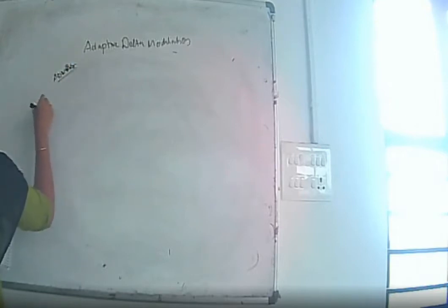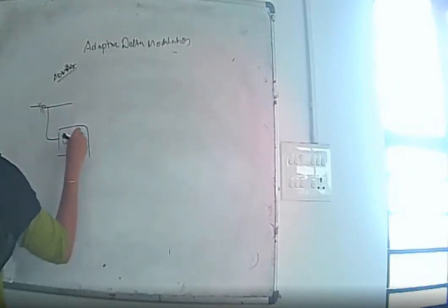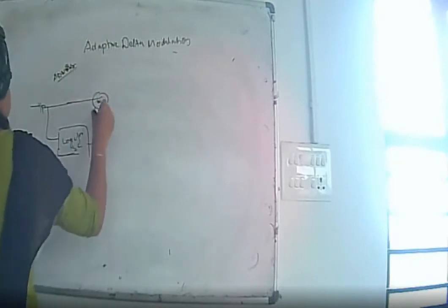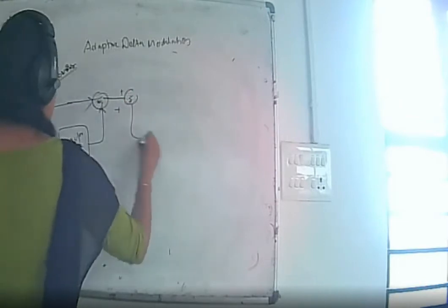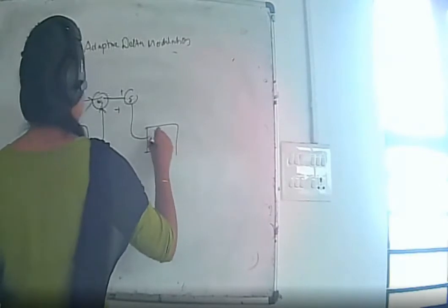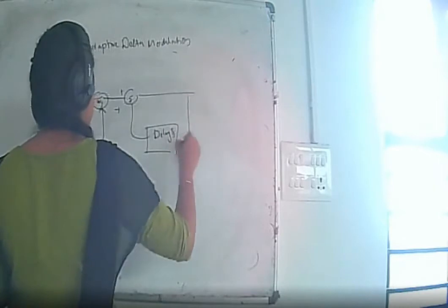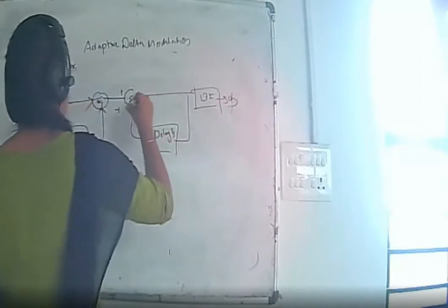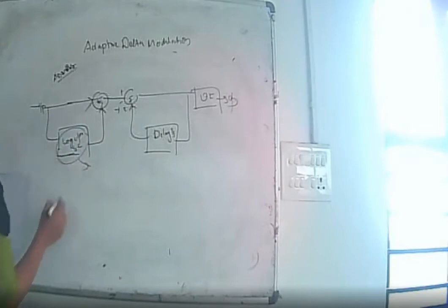Going on to the ADM receiver, we have input and we have a logic for step size control. Step size control, whose output is given to our accumulator side, same as that of the delta modulator receiver. We have a low pass filter and we have the output. The only change in the receiver is that there is an extra block called logic for step size control in the receiver side.